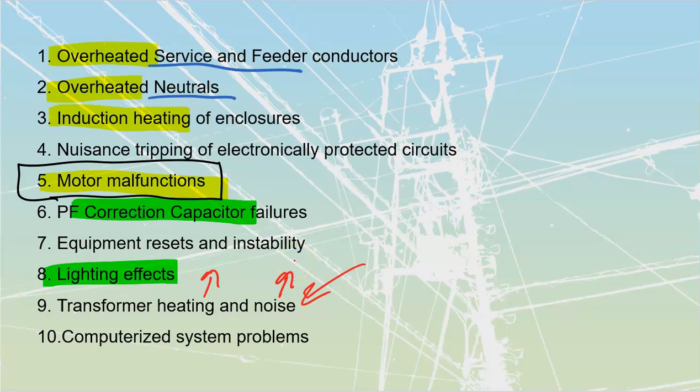Once again, it's going to be more of a harsh sort of magnetic hum. You should have a gentle hum that comes off of your transformers, but if it starts getting a real harsh noise, that's a sign of lots of microscopic mechanical movement inside, and that you've probably got some issues. If you get a proper type of transformer, we're going to have these K-rated transformers that we'll talk about later on. K-rated transformers are going to allow us to pass nonlinear loads, or crap type of loads, through without too much effect.